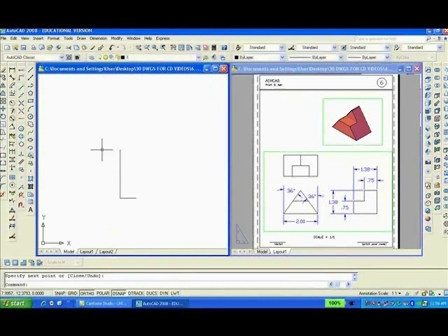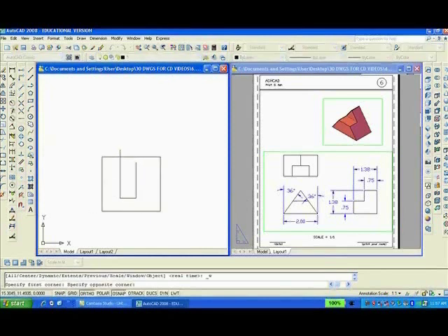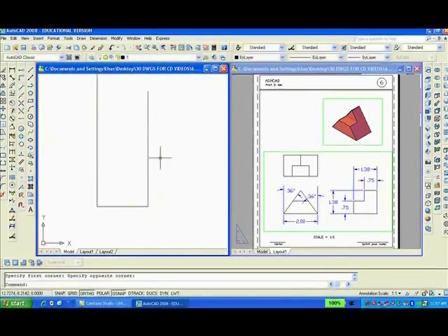I can also draw another line to repeat the command from here up, doesn't matter. I'll zoom with the window to enlarge it. I'm going to rotate, RO enter. I'll rotate the line on the left from its base point counterclockwise, so it's simply 36.